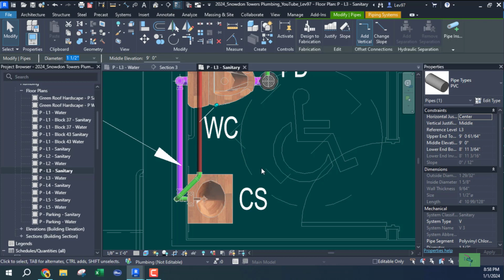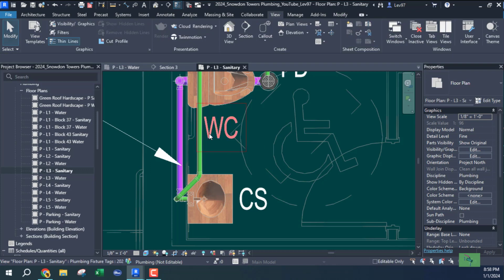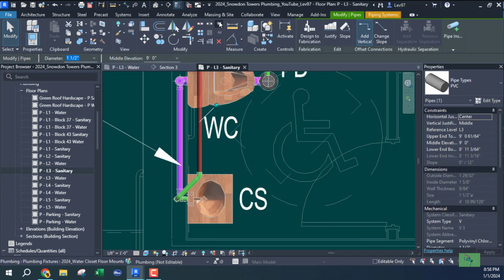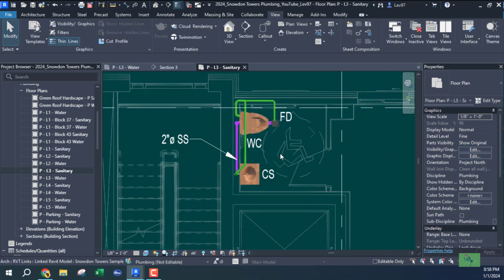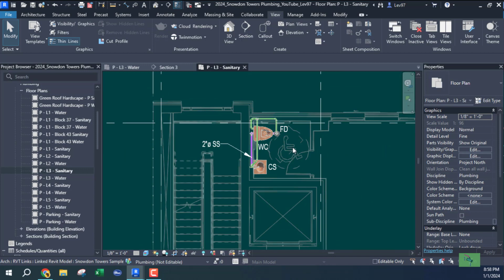Okay. So it's not going anywhere. It's pinned. Let me unpin it because I do want it to go somewhere. I just want to call out the fact that if there are pipes that you don't want moved, under any circumstances, you can pin them. Okay? So let's go back and see if I can get to this water problem.